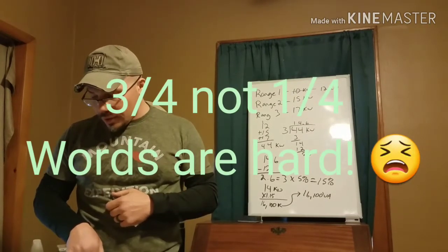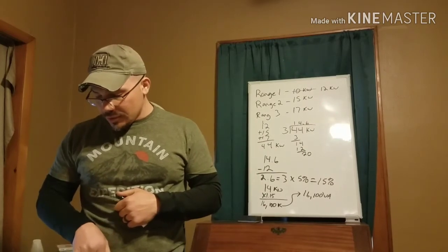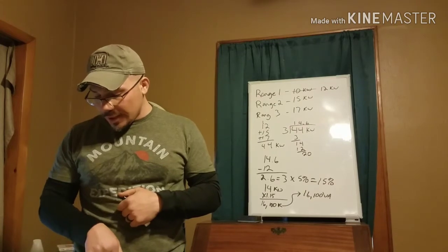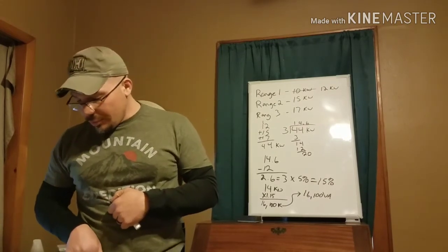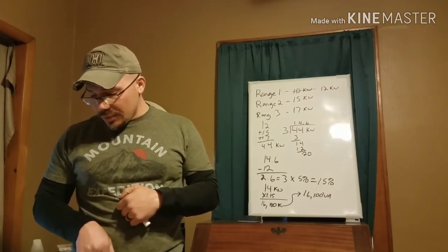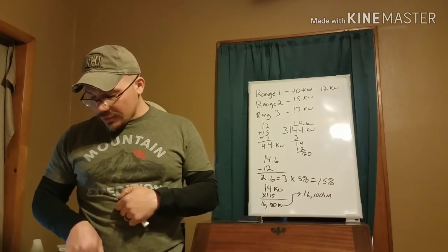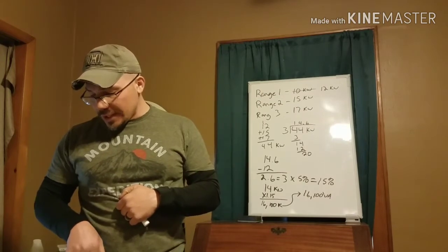In lieu of the method in column 3, it shall be permissible to add the nameplate ratings of the household cooking appliances of more than 1 kilowatt, but not more than 8 3/4 kilowatt, and multiply the sum by the demand factor specified in column A or B for the given number of appliances. Where the rating of cooking appliances falls under both column A and B, the demand factors for each column shall be applied to the appliances for that column, and the results added together.